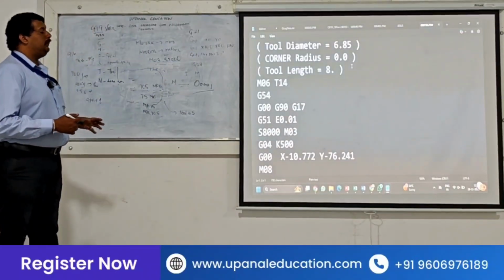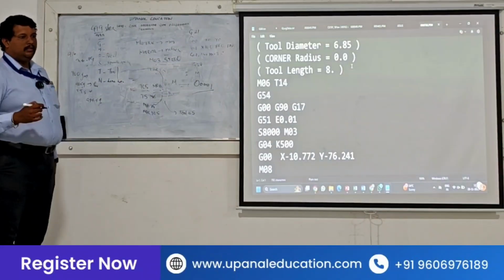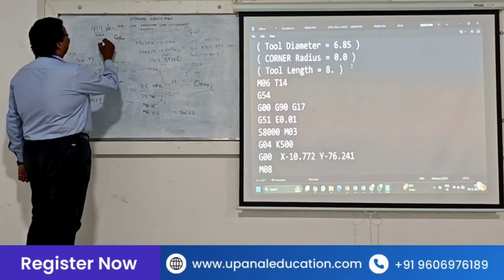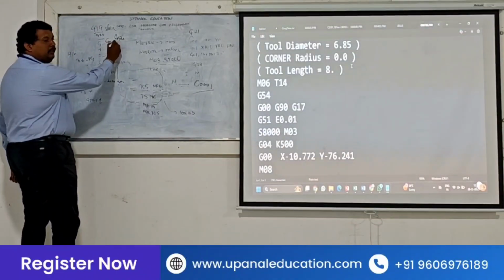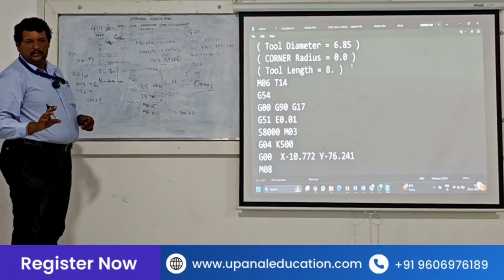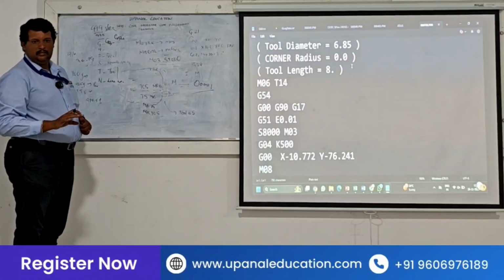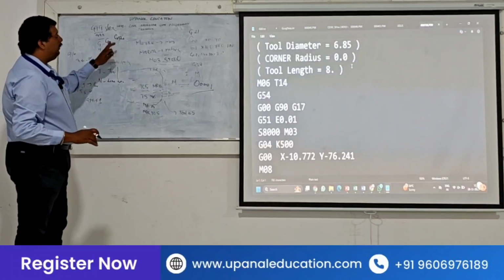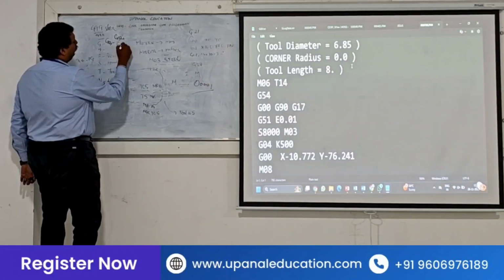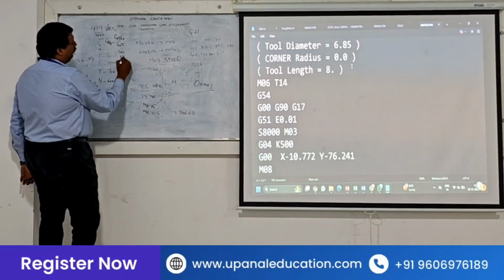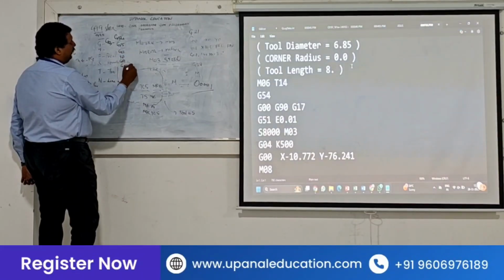So what do we do? We use work coordinates. What are work coordinates? We have G54. G53 will be machine coordinates, that we cannot change. G53 is machine coordinates. From G54, we have G54, G55, G56, G57, G58, G59.